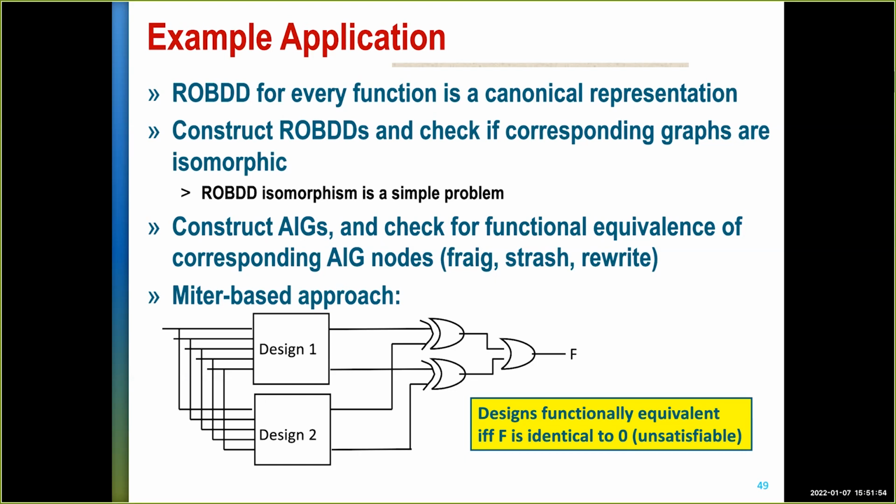So this is one simple way of taking care of arbitrarily many outputs by just adding these few extra gates and then just calling one SAT check rather than as many SAT checks as there are outputs. Now, in principle this should work if your SAT solver can handle it. Building the AIGs is typically not a problem, because their size is linear in the sizes of these designs.